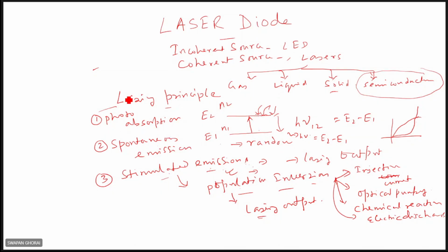Right. And also in this context, we have seen when the LED is modulated with some signals, the modulation rate is limited by the diffusion capacitance, that is due to the stored charges. This modulation bandwidth can be determined if you know the effective carrier lifetimes. Modulation bandwidth is inversely proportional to the effective lifetimes. Now we'll see the laser diodes.